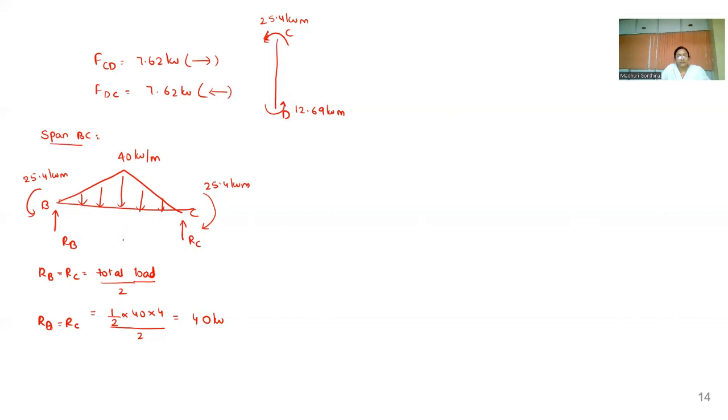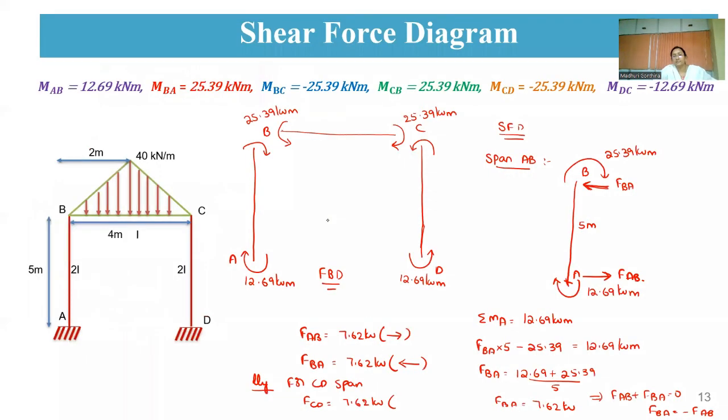Now at this point, we need to draw a shear force diagram. So for the shear force diagram, there is no need of the moments acting, only for this reaction. As we are having equal moments at B and C points, whichever way we take, both get compensated. Therefore, we are getting only the 40 kilonewton reactions. Due to these moments as well as due to this external loading, we are getting only the 40 kilonewton. So now how to draw a shear force diagram.